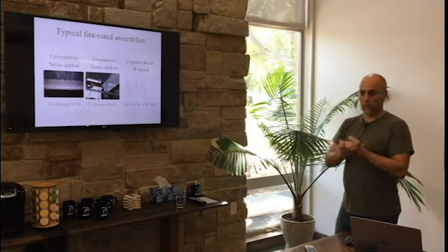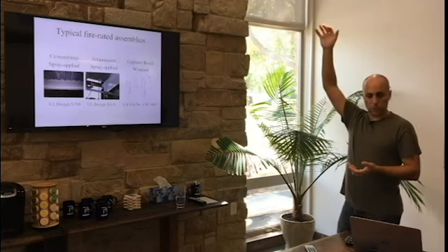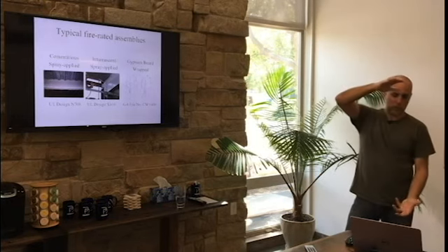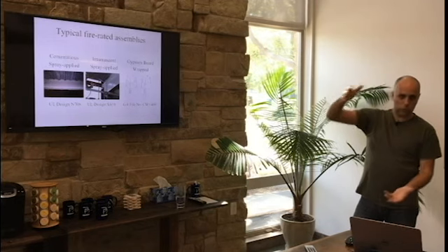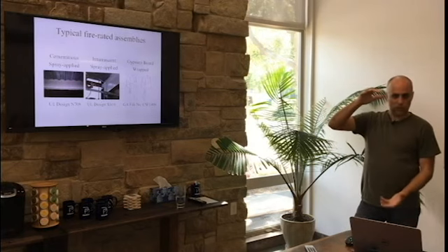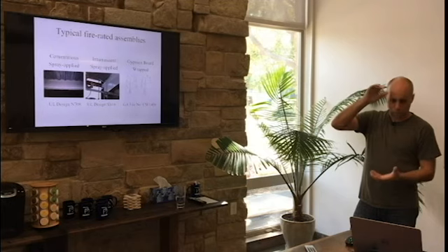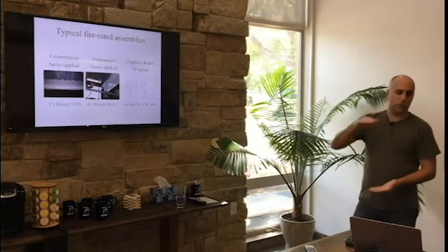You cannot stop it. Bearing walls, bottom plate to top plate. The top plate could be in the attic. Doesn't matter. If you were to take that wall out of its current situation and it's only got gypboard halfway up, it would fail in the furnace. That's the way you have to look at it. If you were to take whatever that element is, separate it out by itself, if you didn't protect it per the assembly for the whole thing, it would fail if it was tested. Because it wasn't tested in an attic. It was tested on its own up against the furnace.